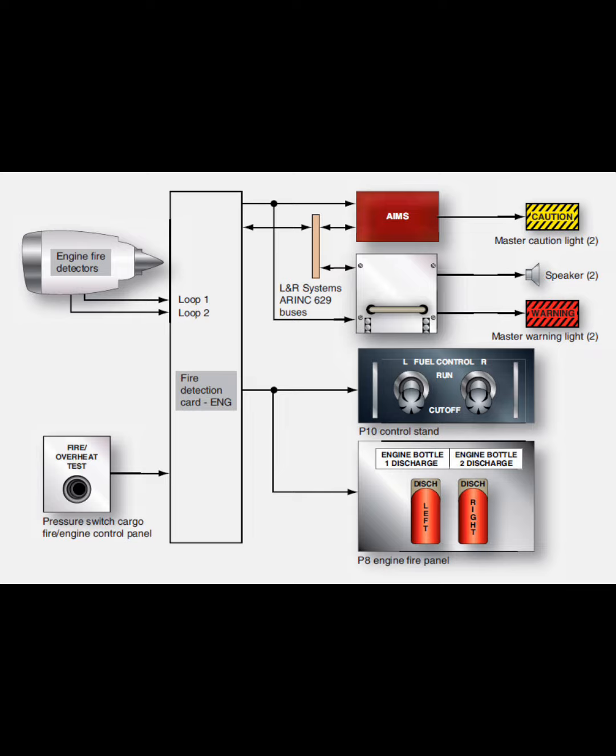When using a thermocouple type fire detection system, what happens if the engine overheats slowly? It will not give a warning. Rate of temperature rise. How many thermocouples are required for engine fire detection? Depends on the size of the fire zone.